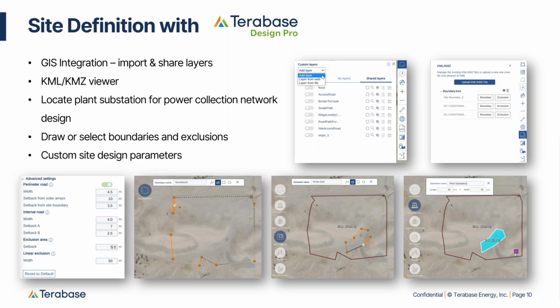You'll need to define your site substation because Design Pro will wire up all your solar panels to inverters and then connect those inverters to the substation in order to calculate cable lengths and trenching requirements. You can also customize your site design parameters such as the road widths and exclusion area setbacks and linear exclusion setbacks as well.